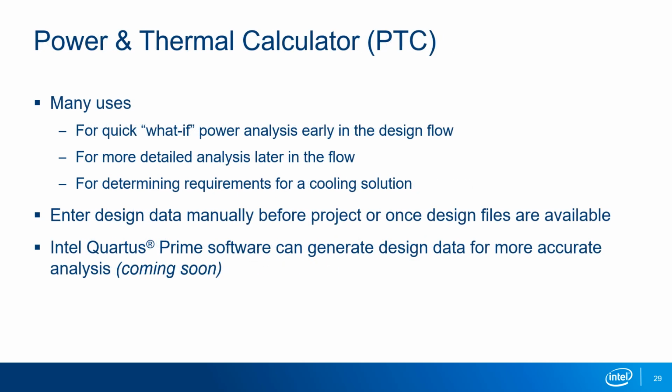The PTC allows you to perform early estimates of power even before a project or any design files have been created. If a project is available, accurate information from the project itself can be taken from the Intel Quartus Prime compilation report and entered into the PTC. This provides a more accurate power analysis.